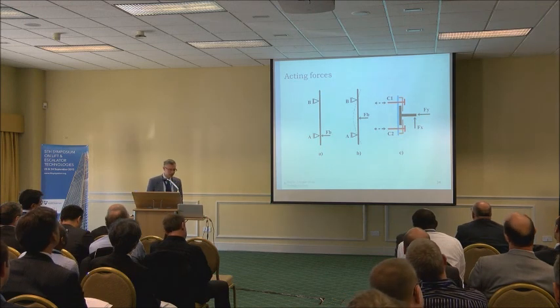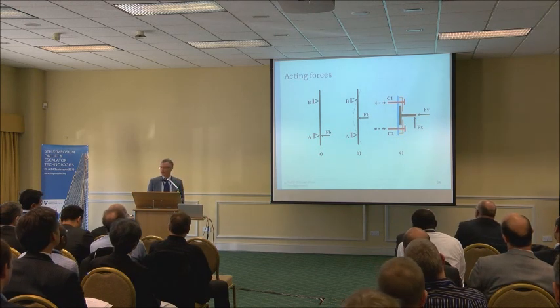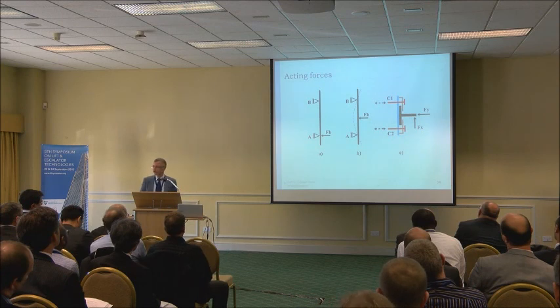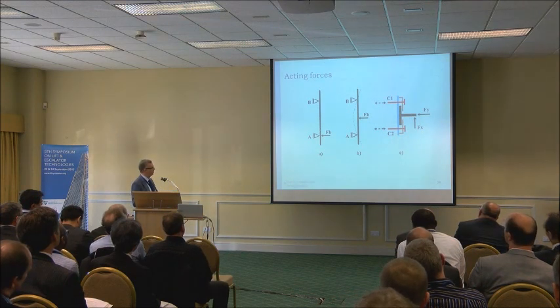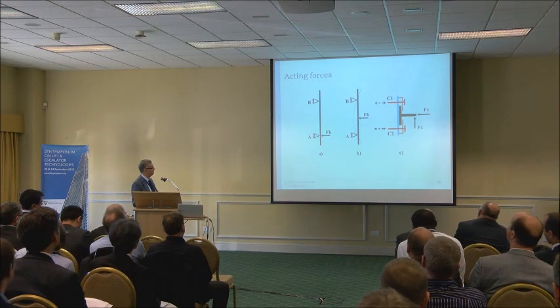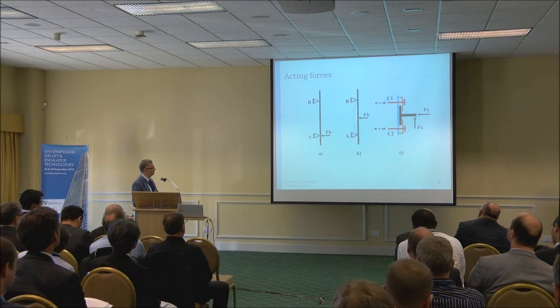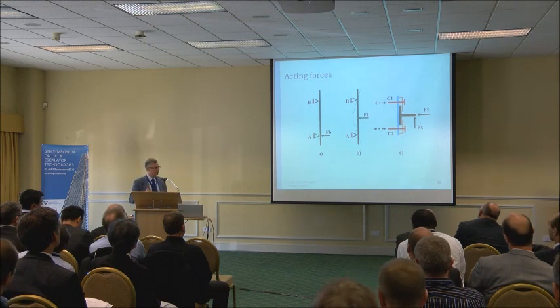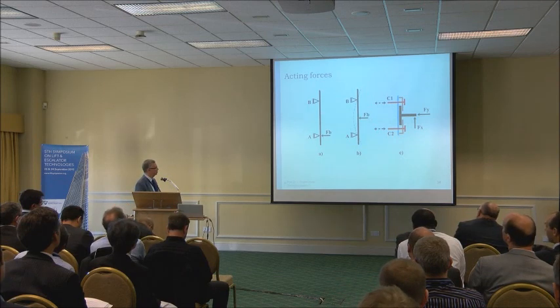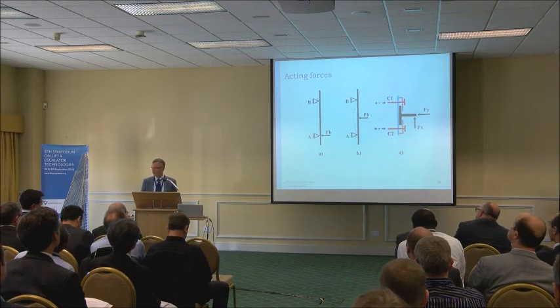And we increase the forces, acting forces, during the safety gear operation. We try to stop the car, the test car, on the bracket at the same level, and we try to stop using the safety gear in the middle of 2 brackets. So we're going to see the effects.